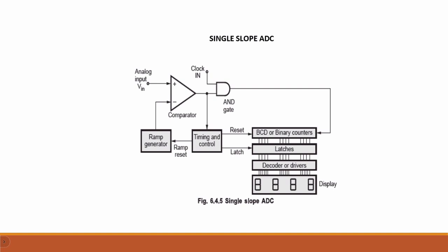Now also the analog input voltage is higher, so again it will produce 1 in the comparator output. Again the AND gate will produce 1 in the output. The counter again moves forward one step. Now it counts to the step of 2. So 2 will be displayed in the LED display.